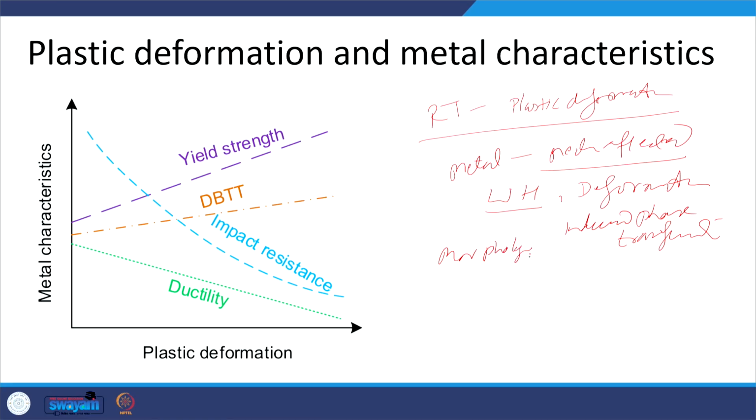So, we get a change in the phases, we get the change in the size and shape, the geometry of the grains, and even the work hardening effect in terms of the increased dislocation density is also observed. So, these factors in combination affect the mechanical properties significantly.